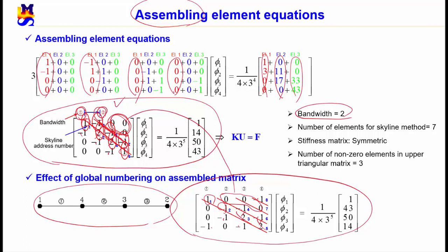When we use a traditional skyline method, we save the elements of stiffness matrix and the skyline formed by non-zero elements. For example, I attach the order, that is, the number in blue, in the example matrix. You can see from comparison of this and this matrix that the number of arrays in the skyline method is also dependent on node numbering. Sparse matrix techniques are also inherently appropriate to solve the finite element equations. In these cases, only non-zero elements with their indices for address are saved, and the number of arrays needed is independent of the node numbering.